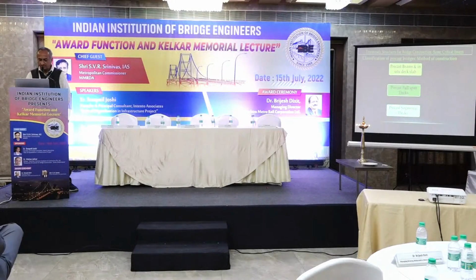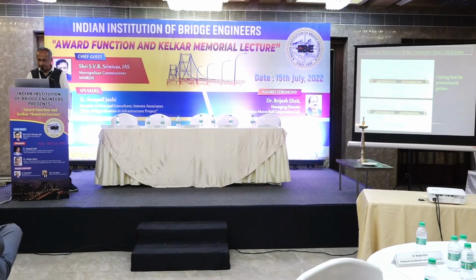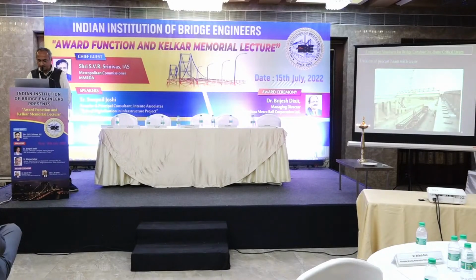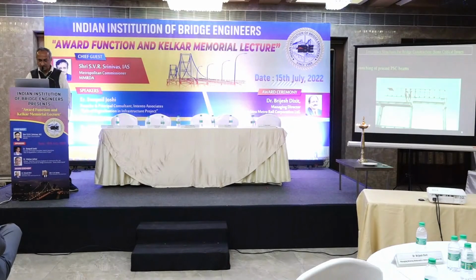Precast decks can be precast beams, full span decks, or precast segmental decks. The pre-tensioned girders were extensively used for Mumbai flyovers, and probably everybody is aware of various examples of this technology. This is just a pre-tensioning bed. You can see the jacks which are used for extending the strands before pouring the concrete. This is an example of erection of a beam using a crane.